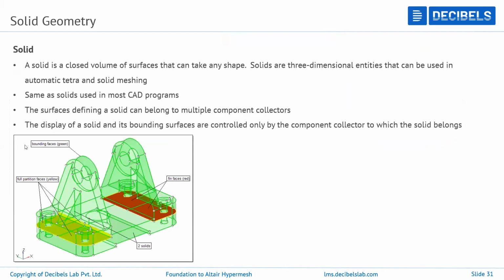This is how our solid geometry looks. All the geometry for CAE purposes, or from any design CAD, we will get as solid only. All the components will come with solid geometry only. If we require the solid geometry, we will carry it with us. If not, we will delete it. Usually, for creating elements, we do not carry the solid with us. As a CAE engineer, we will not carry the solid elements,